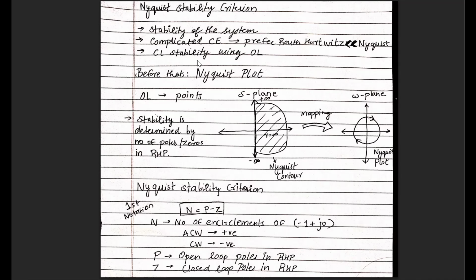This part of the notation is very much aligned with finding out the closed loop stability. And usually you should use this formula when you have information about the closed loop system's poles and zeros. Again, I'm repeating: you take this notation if in the question there is information about the poles and zeros of the closed loop system.